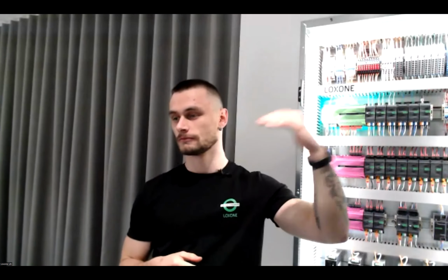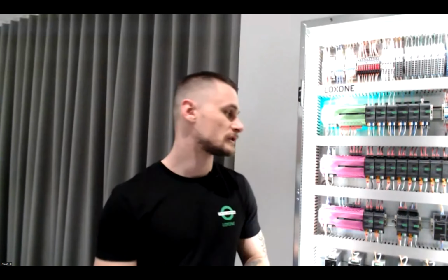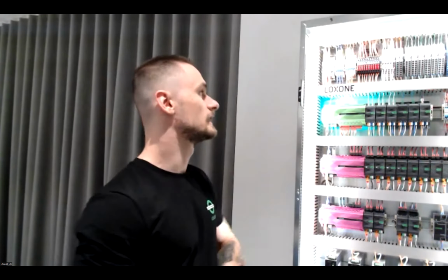Why is that important? Well, I'm pretty sure that all of you can tell me. But why is that information important? Because if you have a potential difference between different circuits, let's say you have two power supplies and the grounds are not linked, you can have up to 48 volts going on that circuit. So we can damage devices, we can over voltage devices. That's why it's super important to connect all your grounds. Now, going to the next section.